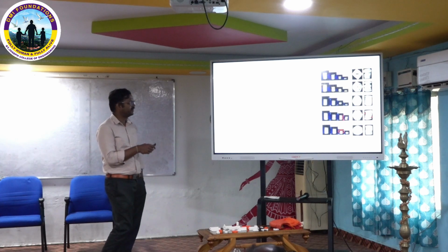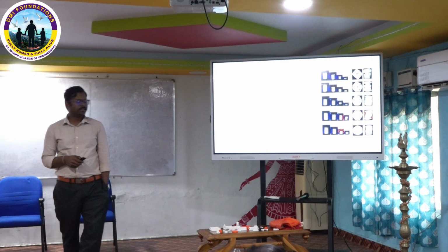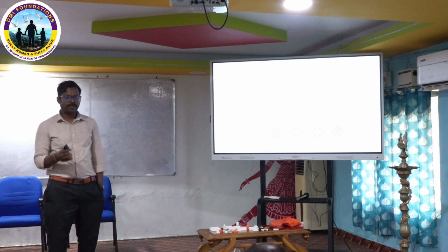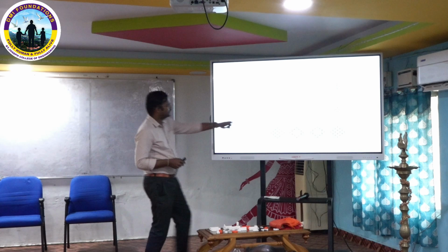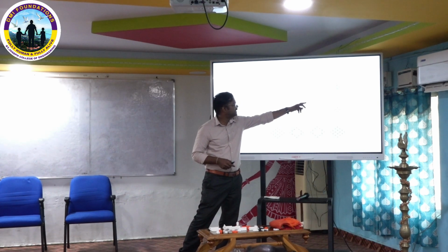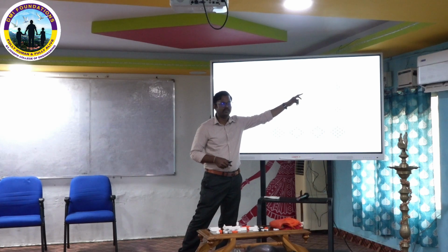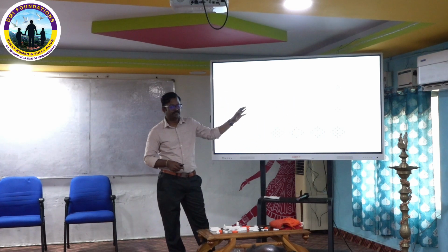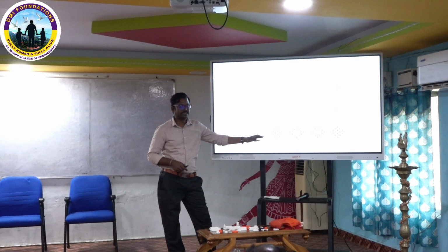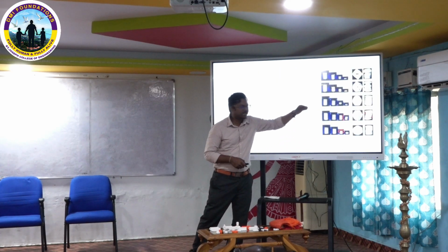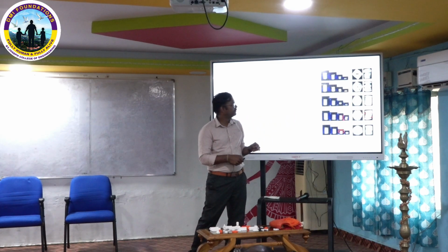So this is the deformation behavior I observed. What I observed is that all the structures give progressive failure. But when I compressed these two structures, CK and CO, what it means is that CK has a simple cubic lattice in the outer shell and a Kelvin lattice in the inner shell. Like this I formulated these designs. When I compress all the designs, all are showing progressive failure, each and every layer.